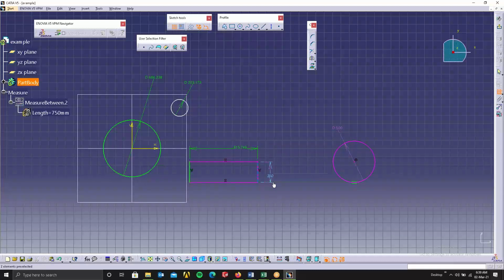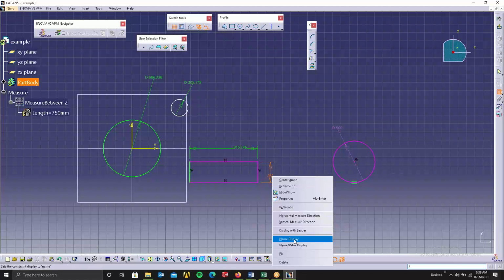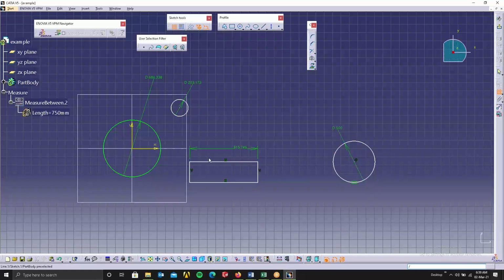You can see this value is not taken, so delete this. It's already there. And one more thing, to constrain anything, you should take the vertical and horizontal lines, which are the origin, as the reference. If you take this reference, your things will be constrained. That's very important.